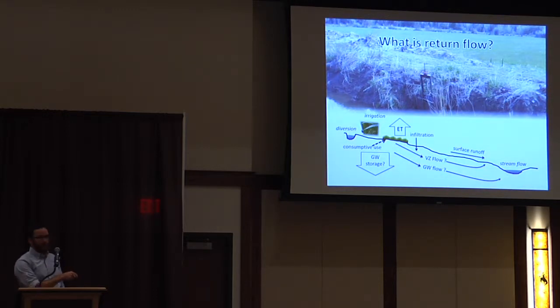And then we have a couple really important arrows. The vadose zone flow, or unsaturated zone flow, the VZ flow one here. This is water flowing through the unsaturated zone, maybe making it back out onto the slope and then continuing as overland flow, or maybe making it directly into the stream. Of course, the other one is saturated zone flow, or groundwater flow.